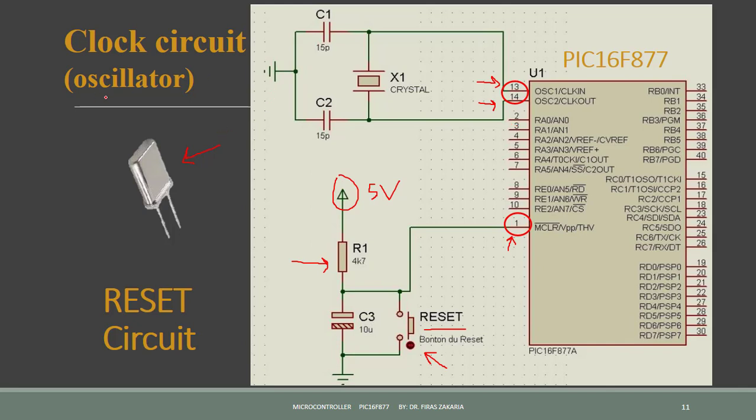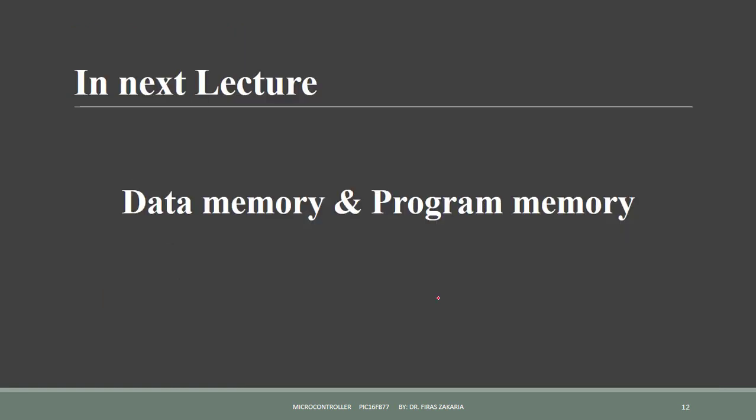So here the clock circuit is very important to the PIC. The PIC will not work without an oscillator. Also, the reset circuit is very important to reset the microcontroller when needed. In the next lecture, we will talk about data memory and program memory in detail.